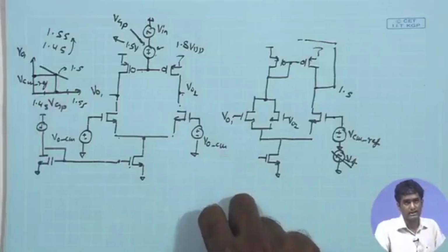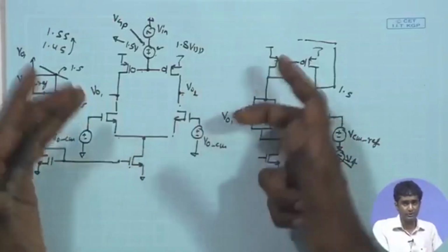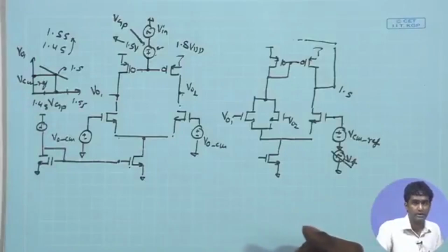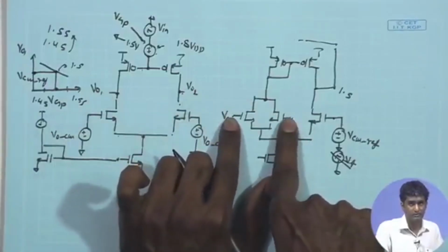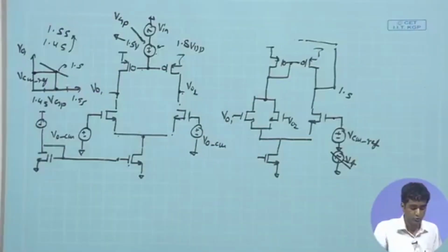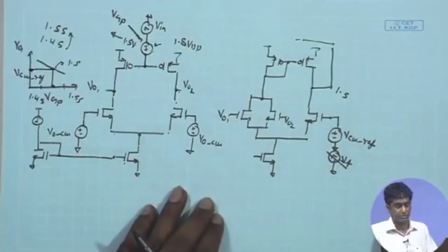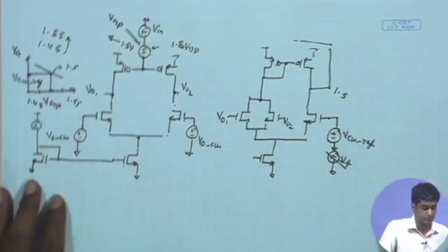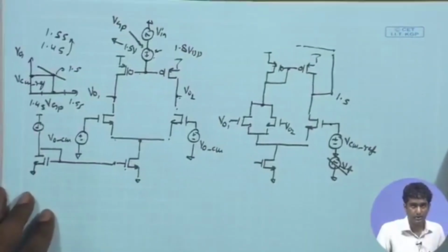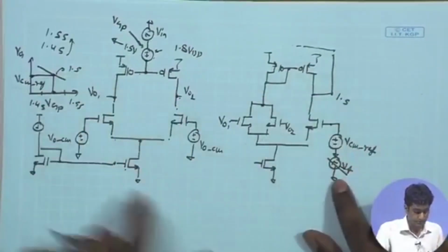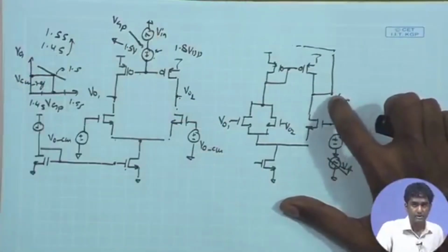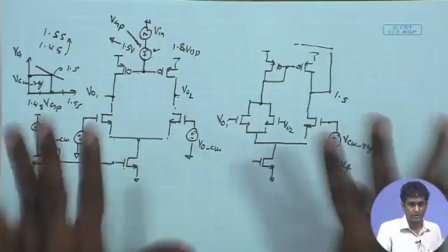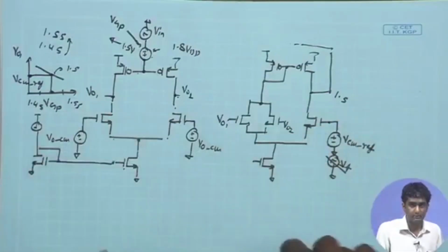So, you will make sure that the output DC point over here is very close to the required DC point under closed loop condition, and we will also make sure that the DC point for these two, VO1 and VO2, is also close to the closed loop condition, and the GMs etc. are very well matched. So, this is the condition you should check while opening the loop, and once you have opened the loop, then of course, you can apply the AC signal over here and look at the final output coming at this point.